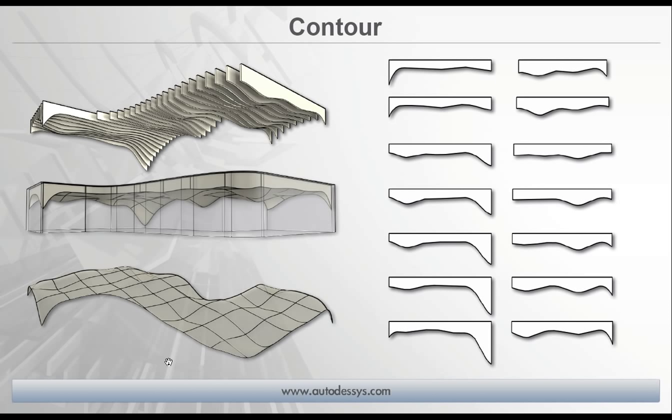As we saw in part 1, there is the contour tool that we used to take a simple NURB surface, we thickened it, and then used the contour tool to cut cross members or our beams for the ceiling. Now there's a couple options in that tool. As you saw, we can leave it at the elevation, but there's also the other option which allowed us to lay them flat on the XY plane. And so now when it automatically lays those out for us, these are true spline cross sections that can be sent to any CNC machine to have them automatically cut out for us.